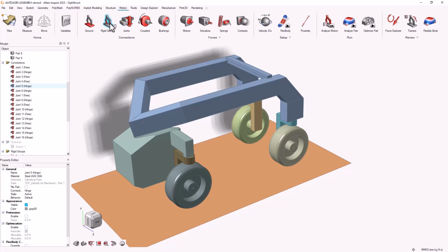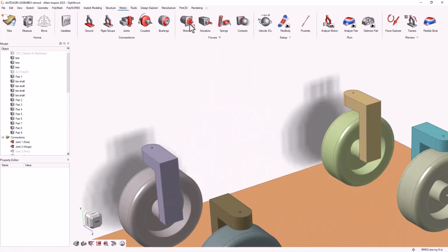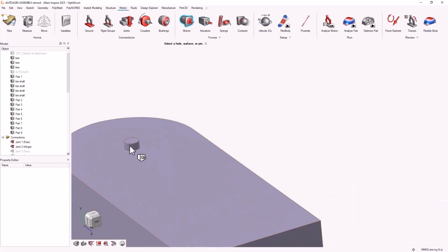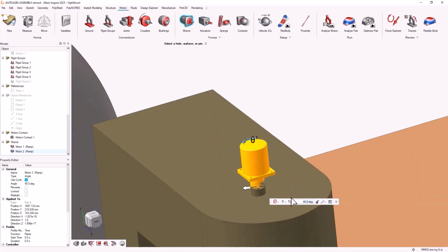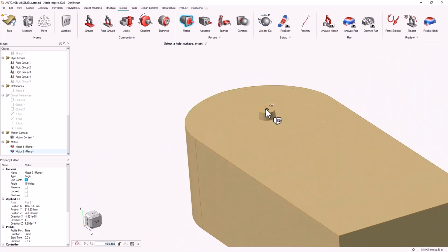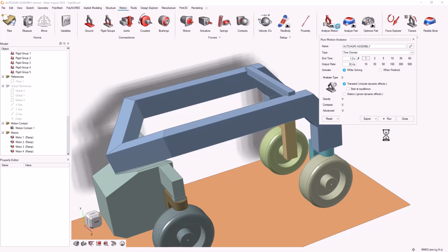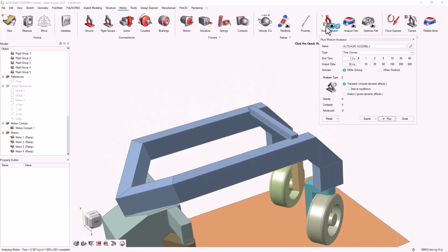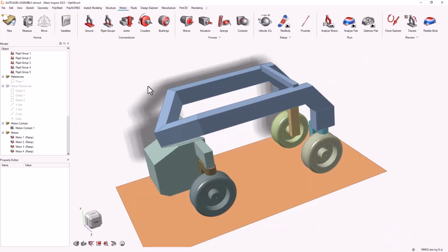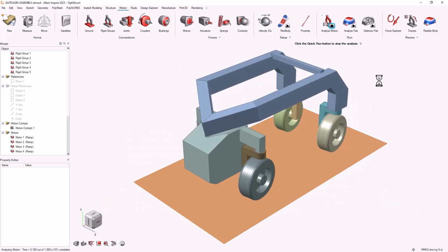The center of gravity was set to the y direction, and the motor tool was selected and applied to all the hinges in the assembly. Next, I assigned titanium as the material for all joints. Then I ran an analysis over 1 second. This helps me spot potential stress concentrations and areas where the joints might be overbuilt or under strain.